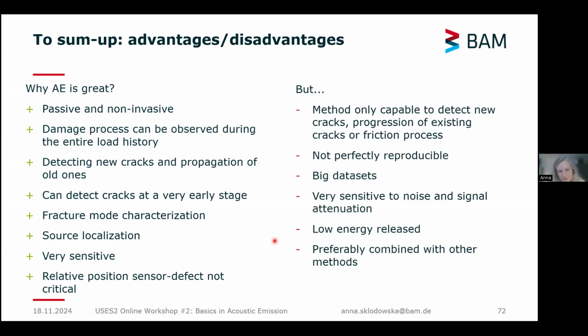However, there are some disadvantages. The method is only capable of detecting new cracks or new processes that are happening. If nothing is happening, basically we don't have any acoustic emission, so we cannot do anything. It's also not perfectly reproducible, and it creates a lot of data, so this is a big data problem at the moment. It's very sensitive, and this is great, but it's very sensitive to noise and signal attenuation, so this is also important to keep in mind. And the acoustic emissions are of very low energy. So this is also a disadvantage.